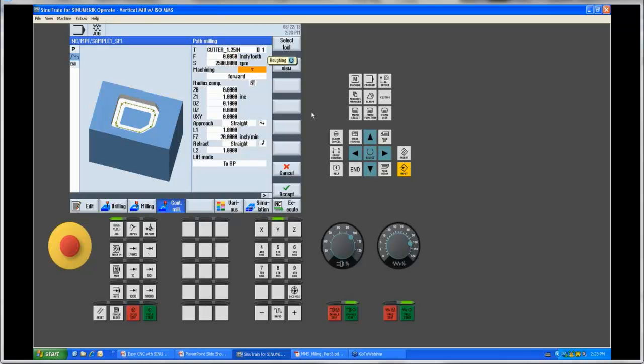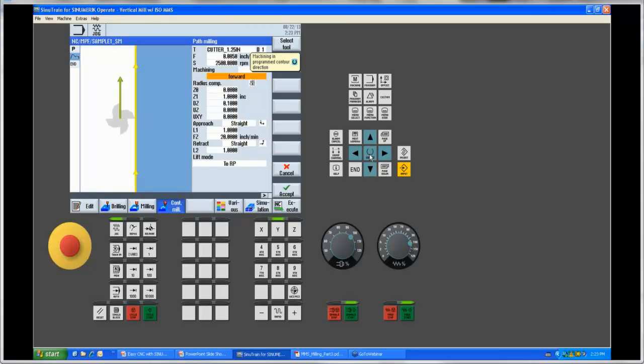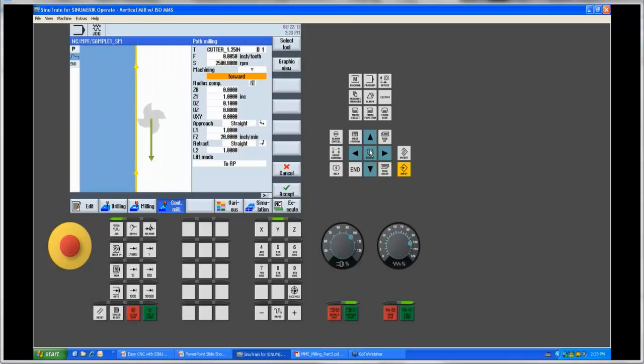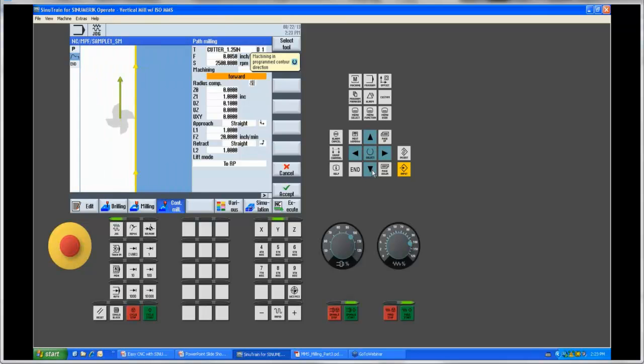Next, we're going to come down to our machining state. That's that little diamond right here, and this tells us whether we're roughing or we're finishing or we're chamfering. So we get a few different options we can do on this profile. I want to rough it out, so I can take multiple passes on it. I can define, do I want to follow the direction the shape was drawn, or do I want to go the opposite way? Well, in this case, I already drew it clockwise, and I want to climb mill, so I'll follow the direction I drew it.